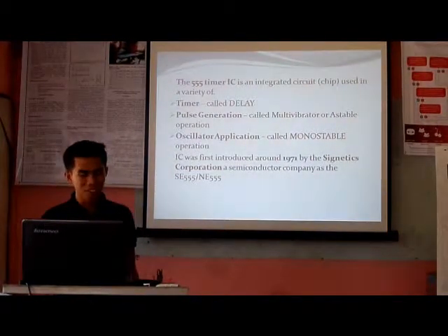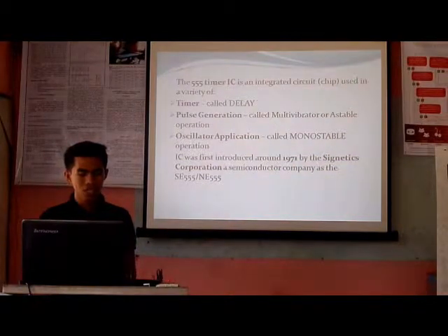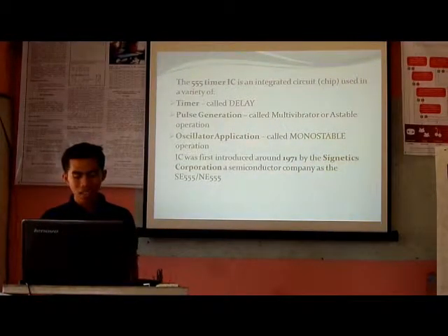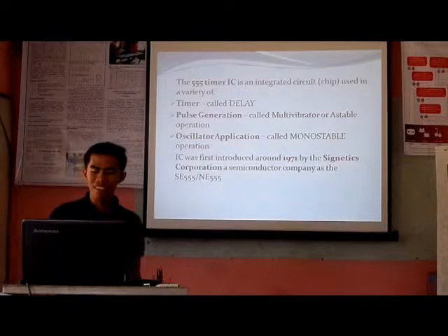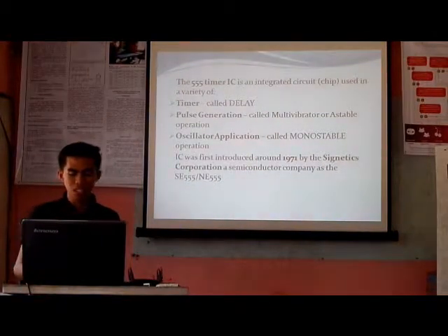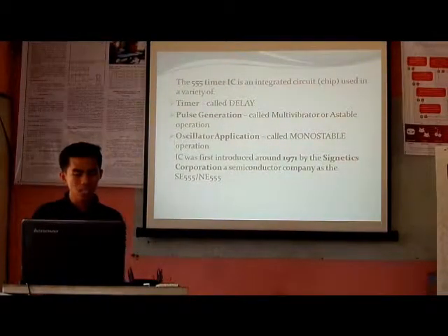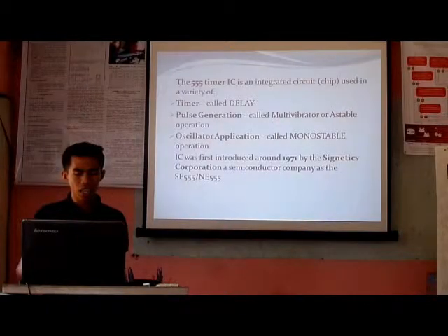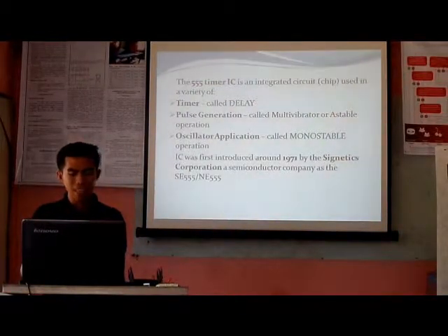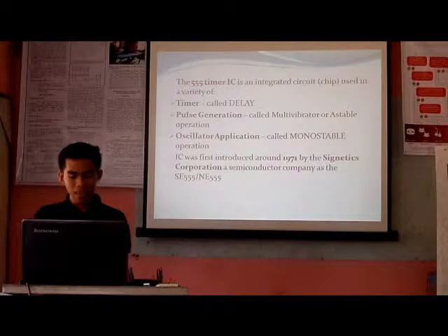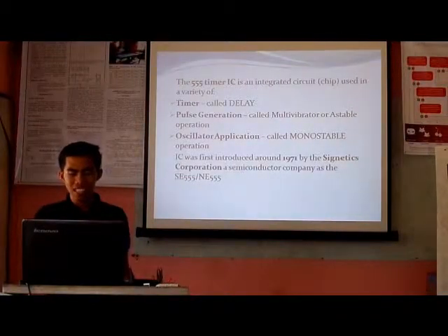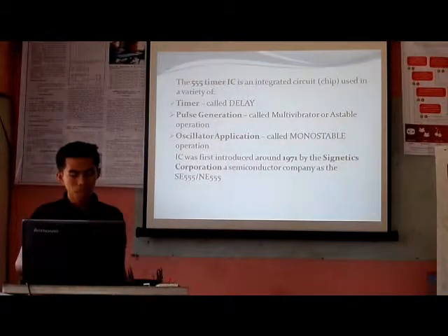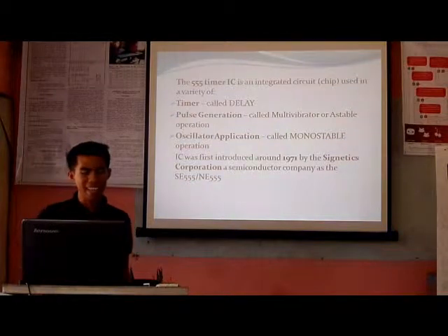The 7555 is designed to cause less supply noise than the classic 555, and the manufacturer claims that it usually does not require a control capacitor, and in many cases does not require a decoupling capacitor on the power supply.